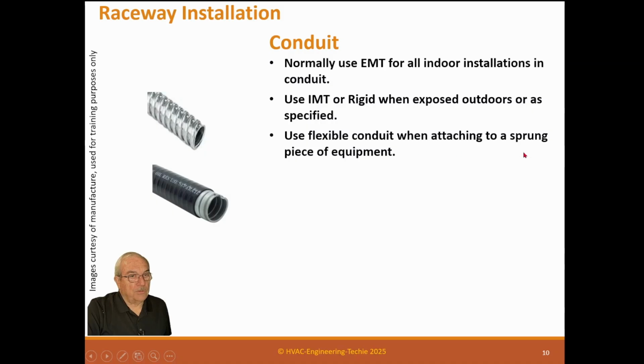Use flexible conduits when attaching to a sprung piece of equipment. If you have equipment that is on springs to keep down vibration, then the electrical connection must also be able to flex. So if it's indoors and it's not exposed to weather, we use a metal flex like that. If it's outdoors, liquid tight is a flexible conduit that has a coating on the outside that makes it weatherproof. Now there is a problem with these, is they'll last about 10 years. And if they're exposed to sun, the sun will actually eat this layer up. So they have to be managed or painted. Most people don't paint them, but that is a problem.